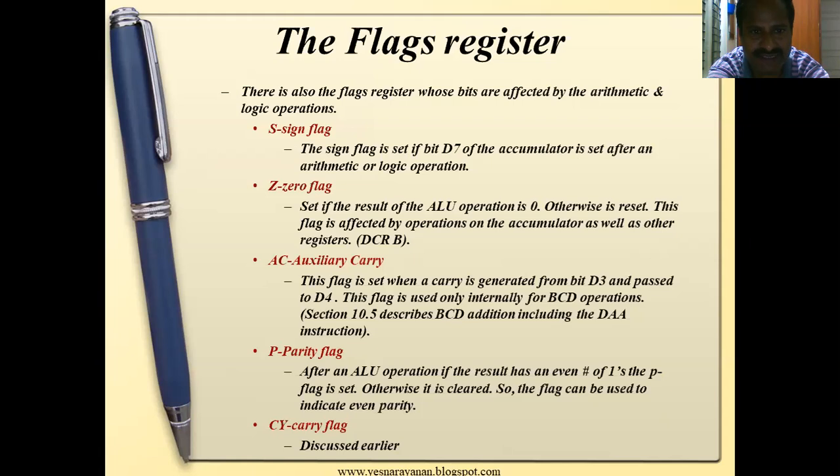Auxiliary carry. This flag is set when a carry is generated from bit D3 and passed to D4. This flag is used only internally for BCD operations. BCD means binary coded decimal operations. Parity flag.